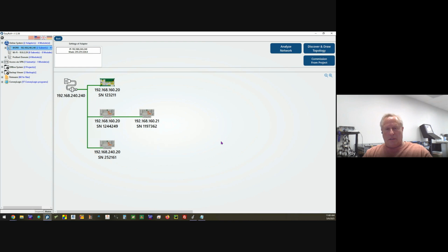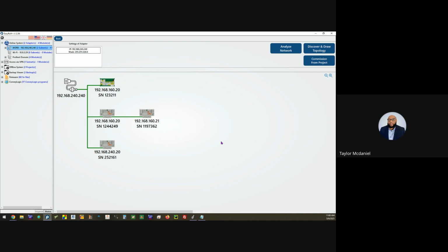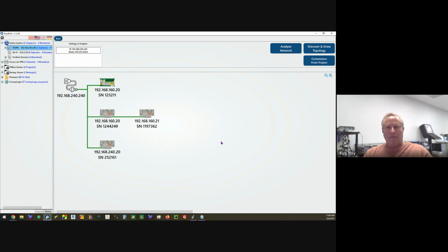Next, node 1 generates a random number. We call that the configuration ID. Lastly, node 1 sets a bit in a register that says first flag on the first module. Once it does that, it passes the data to the next card.